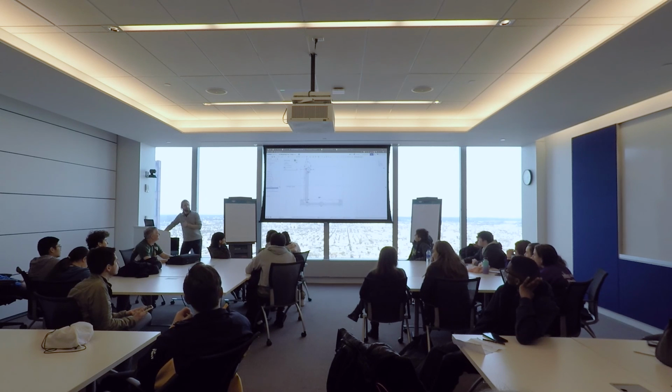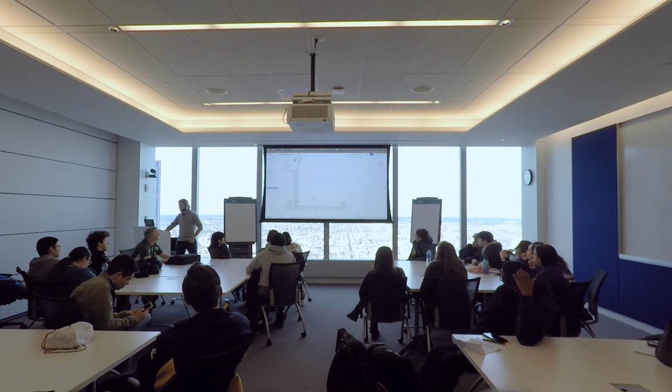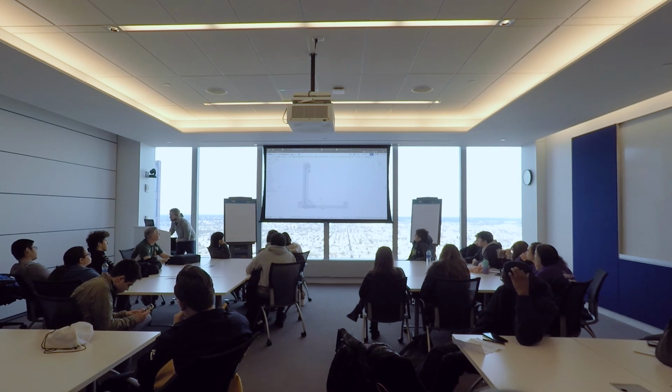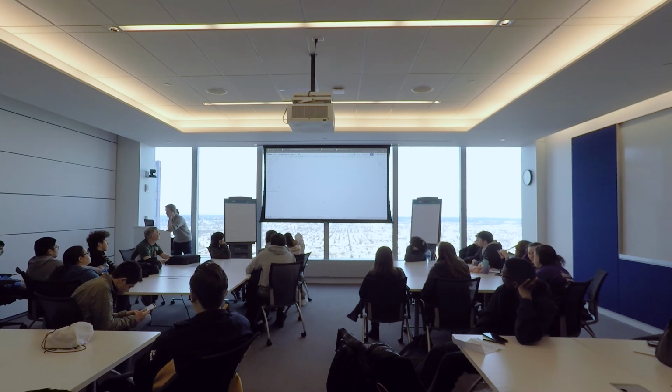But this whole sketch, a relatively simple 2D sketch, now has the capability. It's a conveyor for a 1 inch ball, and maybe it's not a 2 inch roller anymore. Maybe that's what the RD is. That's roller diameter. Okay, that's good to know. So I could come into here, and this roller diameter I can make 1 inch instead of 2 inches, and I would also change that conveyor. So now I can go in here and do a ball diameter of 6 inches. I had 4 inches. It looks like that. And I could do a ball diameter of 8 inches. That looks like that.